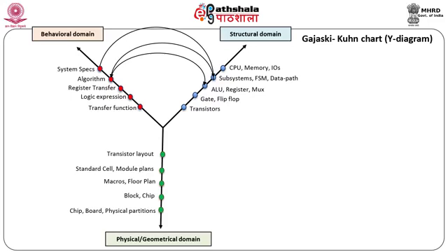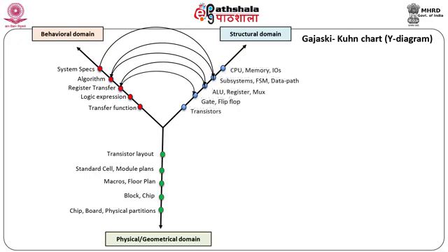This aspect provides a transition from the behavioral to structural domain. Each subpart or subcircuit can further be thought of located on the behavioral axis, which provides next path on structural domain. This process continues until a low level of abstraction is reached. During this top down approach, starting from behavioral domain at top level, the process of design reaches till the bottom of structural domain at transistor level. The IC layout is not considered during this top down design approach.